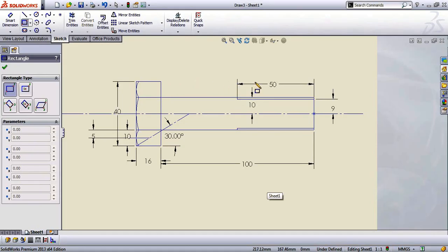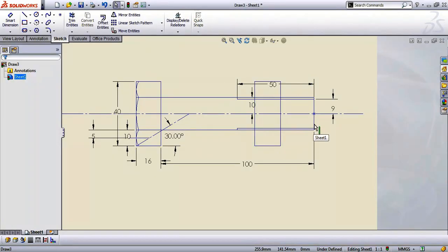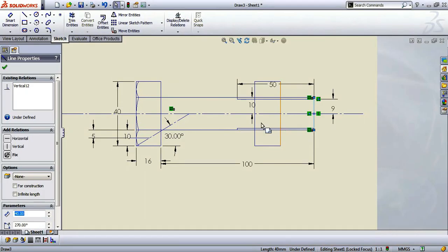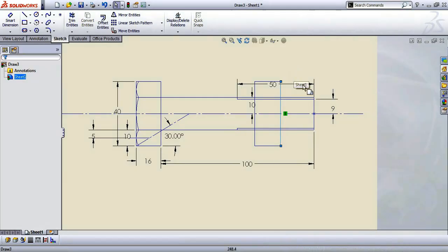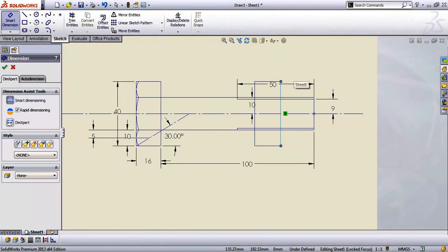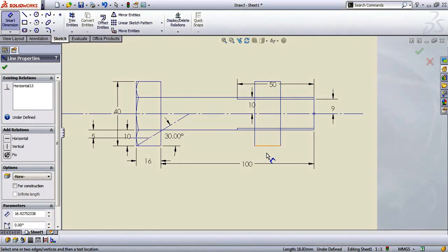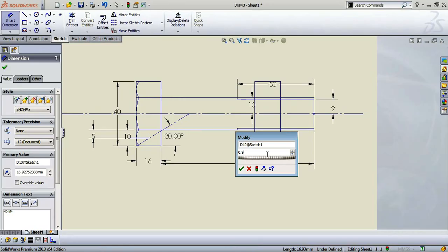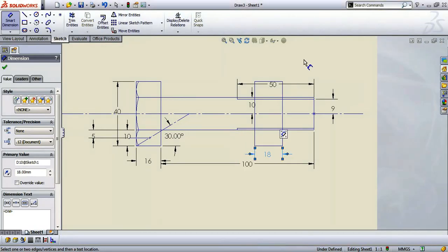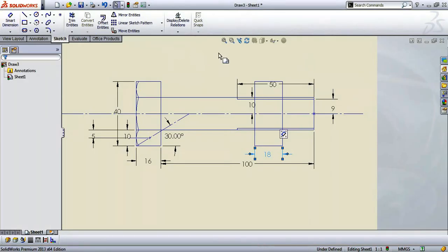You can just take the reference of this line. Nut portion from here you can take at a random distance. Make sure it's not lying on the exact outside of this. Okay, it should be a little bit inside the bolt portion. Okay, now the thickness of the nut will be 0.9 times the diameter. Either of this side, you take this.